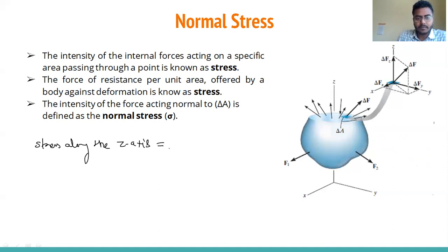The notation is sigma z, which is the limit as delta A goes to 0 of the force in the vertical direction, along the z direction, that is delta Fz divided by delta A.